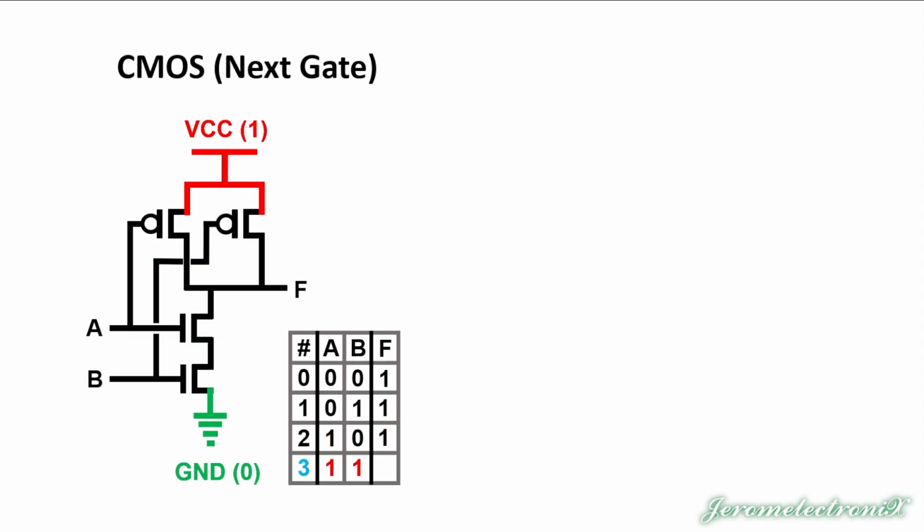All right, this last one, we've got 2 1s going in here, 1 for A and 1 for B. Putting the 1 in through A, it flows horizontally to the NMOS, flows vertically to the PMOS. A 1 on a PMOS blocks the PMOS. A 1 on the NMOS allows flow, but there's nothing to flow through. So let's put the 1 into the input B. 1 into input B, that flows horizontally to the NMOS and flows vertically to the PMOS.